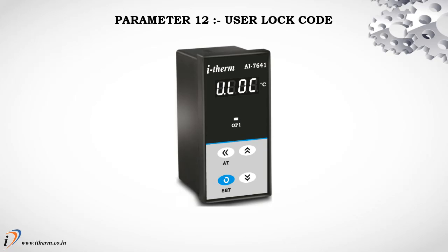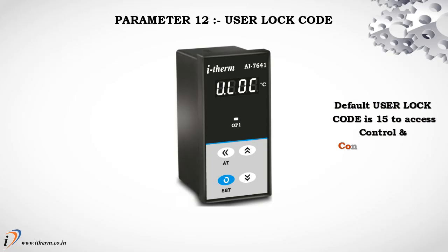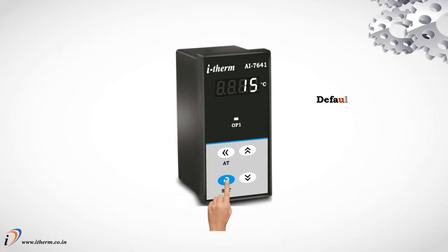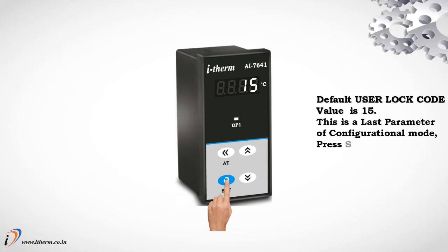Parameter 12, user lock code. Default user lock code is 15 to access control and configuration list. This is the last parameter of configurational mode. Press the set key to enter run mode.